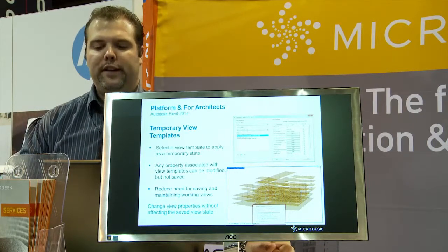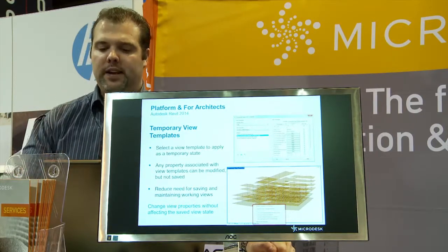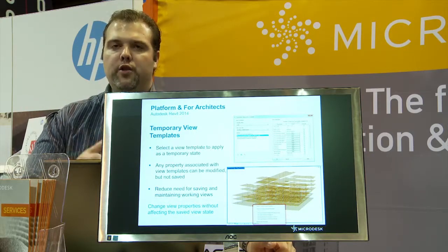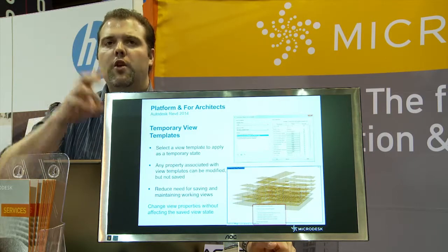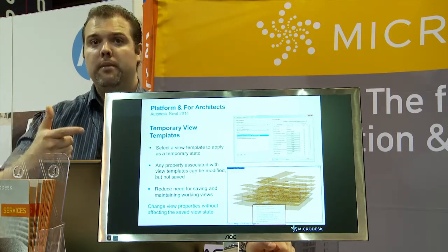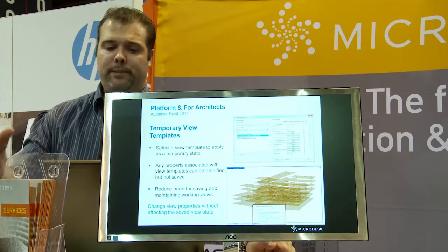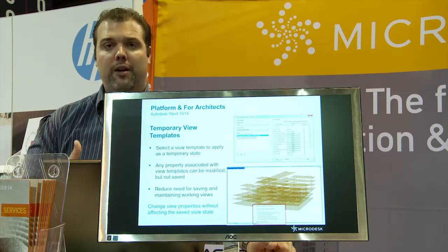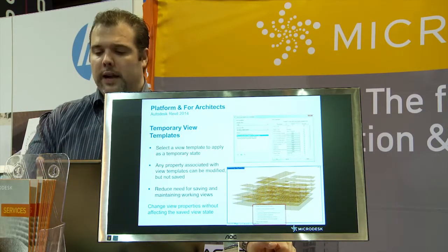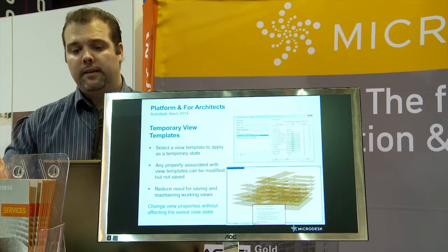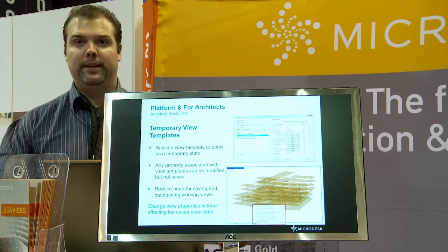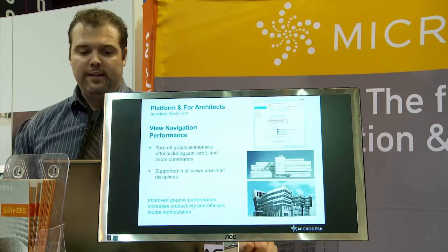So in terms of graphics, let's say you want to clean up the model, find something in the model, section it, or visualize something, it will require you going through a lot of iterations, or applying a view template that later on you had to remember to reapply as it was previously set up, so you have the right graphics. This is something that I know for a fact affected a lot of people that were about to print a whole set for the deadline, and there was stuff that was disappearing because somebody forgot to reapply a view template. So definitely saves a lot of time.